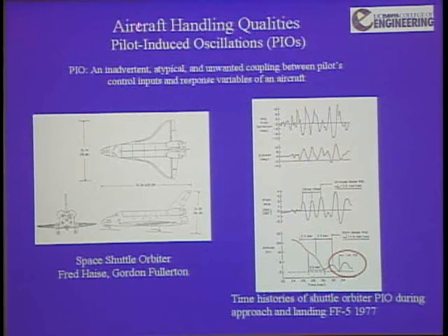Okay. Aircraft handling qualities. There is something called pilot-induced oscillations that you may have heard of. It's a type of inadvertent, atypical, and unwanted coupling between the pilot's control inputs and the response variables of an aircraft. It's nasty. It's dangerous. The first one of those serious ones happened with the space shuttle. Fred Hayes was flying. Gordon Fullerton was second in command, and this was called Free Flight 5.